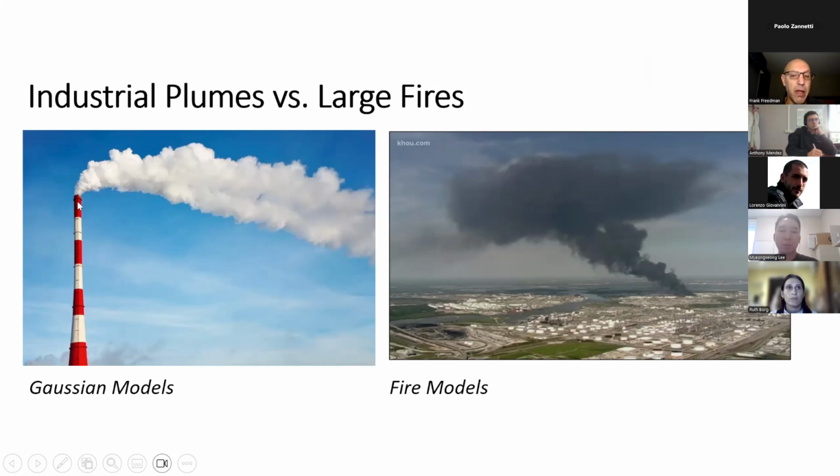Well, the similarities is that, yes, you have an emission from a particular source where there's a flux of mass in the form of air and a small amount of particulate ejected out from a source with some type of volumetric flow outwards. And then eventually the momentum from the ejection gets detrained into the ambient air, and the plume then advects normally with the wind after that point.